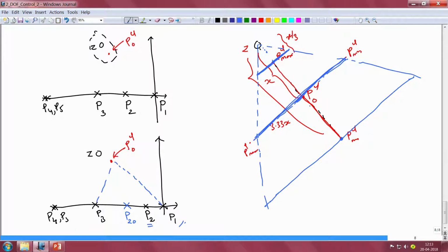So this in turn implies that this line along which the closed loop pole varies due to the variation in the open loop pole position of the plant is going to be once again parallel to the two other lines along which the closed loop pole varies when the plant's gains are at different values. In the one case the plant gain was assumed to be at its nominal value, in the other case the plant gain was assumed to be at its maximum value.